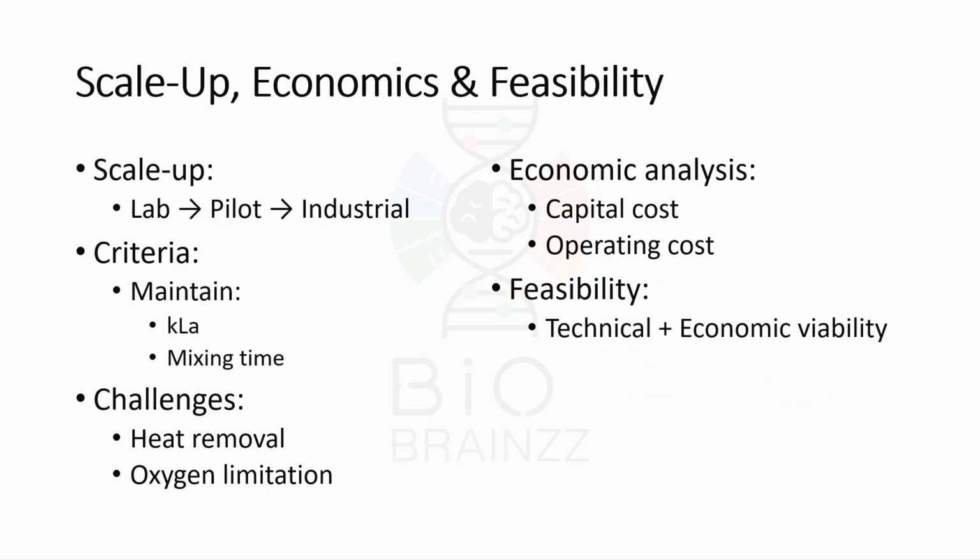Scale up means increasing the process from lab level to industrial level. During this, parameters like mixing and oxygen transfer must be maintained. There are challenges like heat removal and oxygen limitation. Economic analysis includes cost and feasibility to check if the process is profitable.